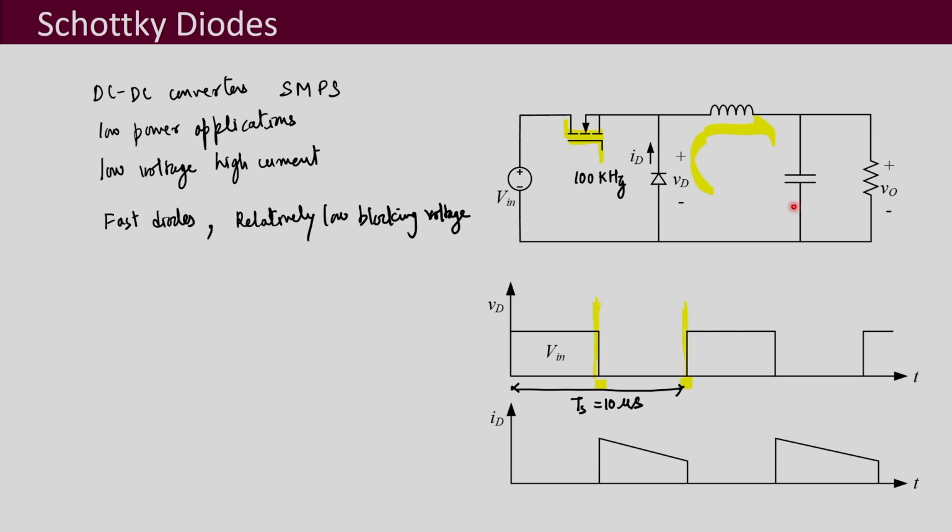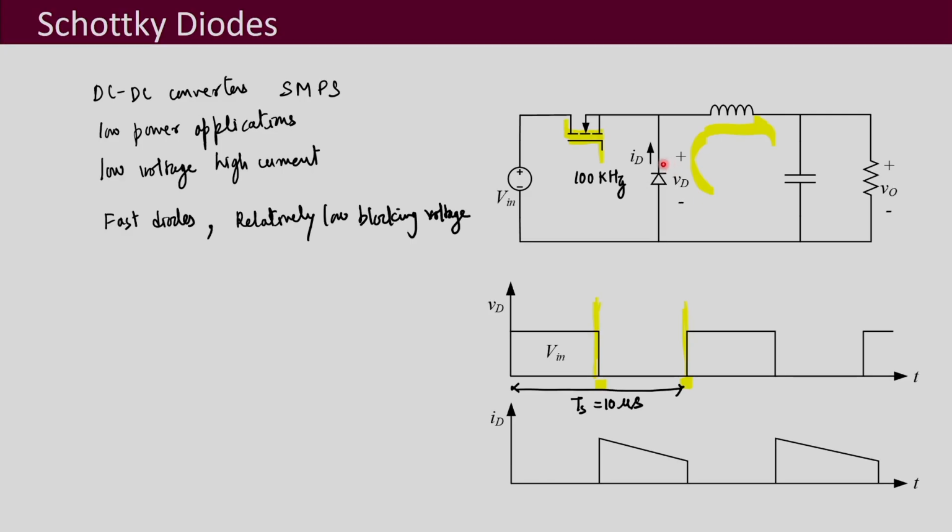We had seen this effect in the LTspice simulation that I had shown you before. So, we would like this on state voltage drop to be ideally 0, and if it cannot be 0 practically, then as small as possible. Low on state voltage drop is good to have in any converter. So, to reduce conduction loss, low on state voltage drop is also a requirement.